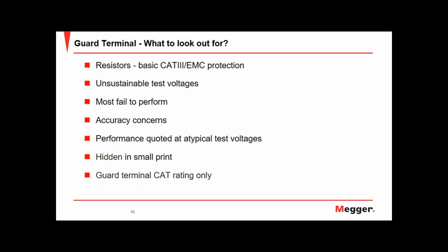Now, also, some people only CAT rate the guard terminal. So make sure that all terminals that you have on your instrument are CAT rated.